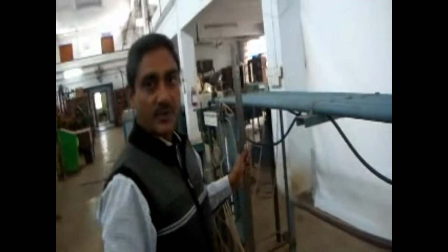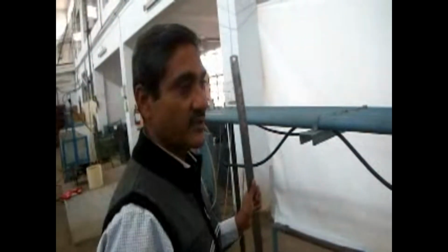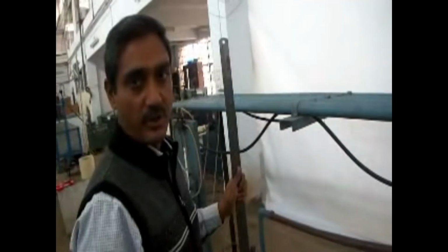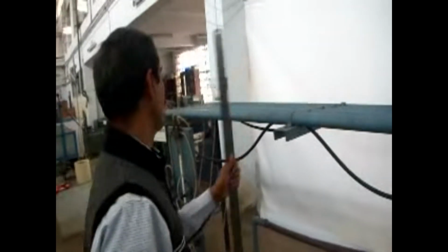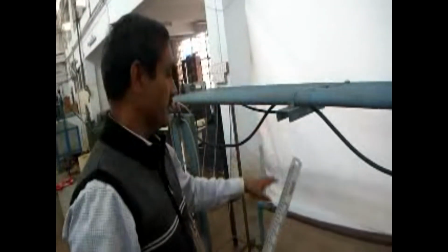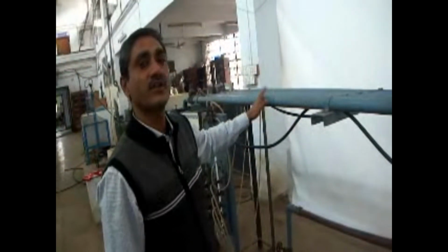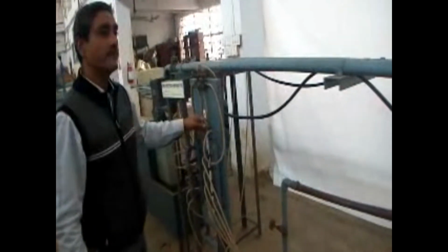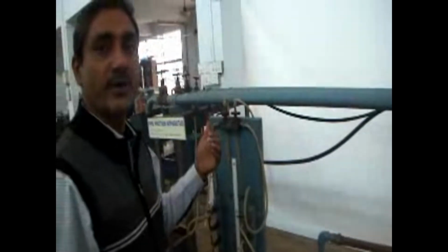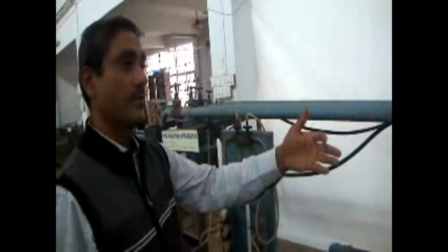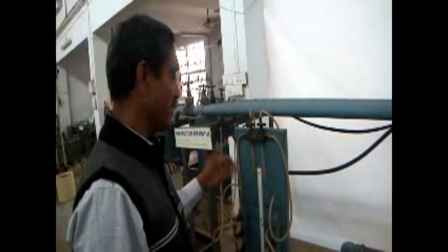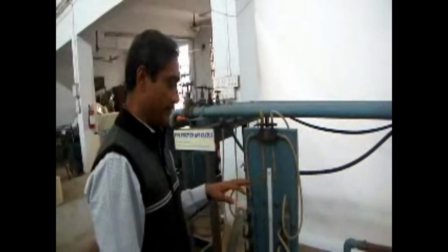Velocity we are getting from discharge per unit time relationship. G we know, 9.81 meter per second square, and diameter of the pipe. So let us find out at least for 3 different discharge condition what is the flow and head difference for this 2.4 meter difference from inflow side to outflow side, that we can measure by using this U-tube manometer, finally to find out coefficient of friction or friction factor of the pipe. So let us start this.